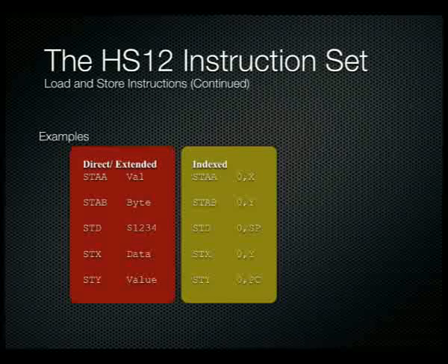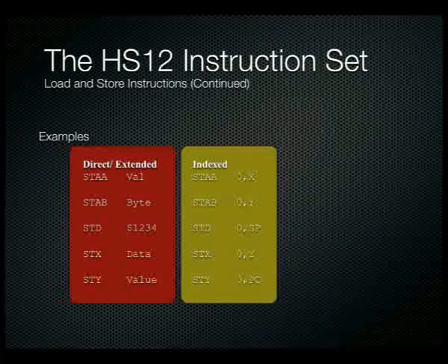And then of course you just simply specify the variable that you want to store that in. And like before, you've got to keep in your mind what the size of that register is. So if it's an 8-bit register, you're only going to end up storing it onto a single 8-bit memory location. If it's a 16-bit register, then you're going to end up storing it onto 2 memory locations. MSB will be in the location you specify. LSB will be in the location directly following that one.